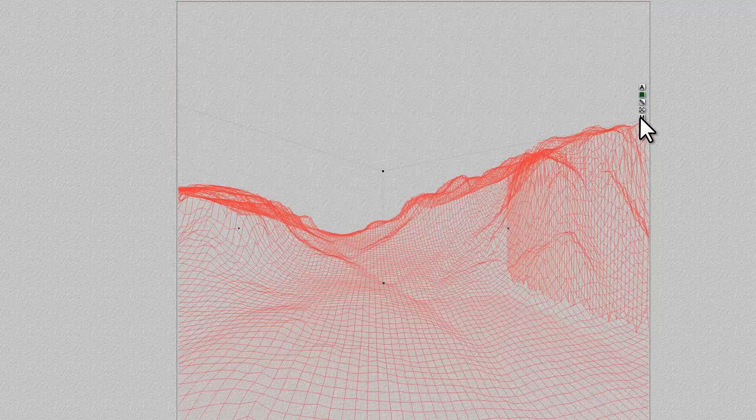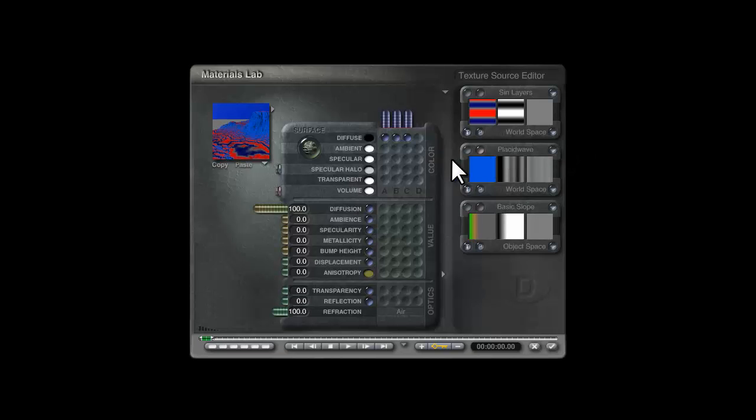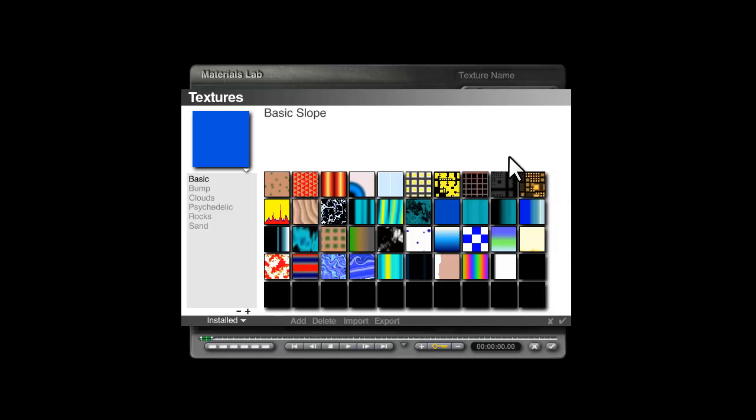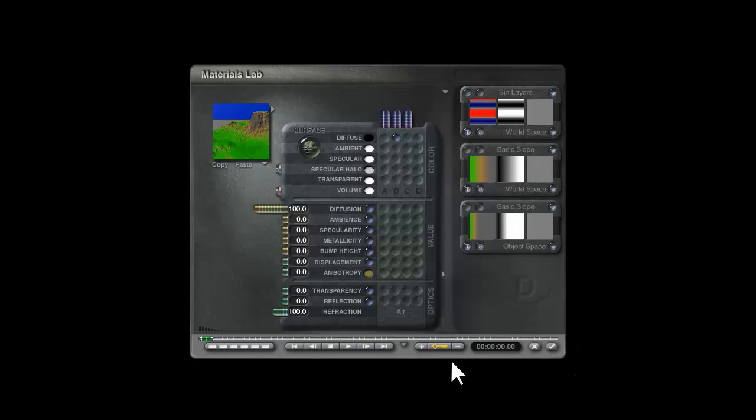So that is my reasoning for wanting to put my curvature filter in here, because I want the curvature filter to affect the rocks and not the ground. But what I shall do, I shall just go back to working in this one channel here, is show you the curvature filtering first, and then we'll isolate it with the slope filter and put something suitable in for the ground afterwards. So I'll hold shift down and click on the name there and bring in a slope filter as the one to adjust, so you can see the effect of the slope filter on its own now.